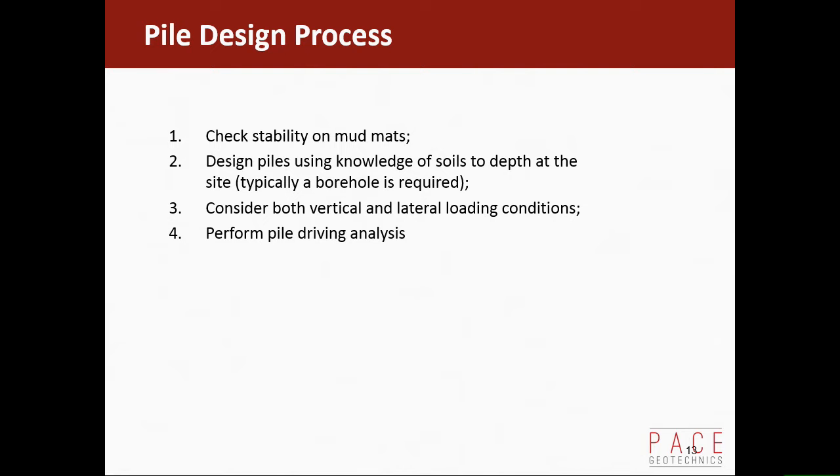One point I didn't make was that another advantage of a small gravity-based type structure is you just need to know something about the soils really in the top 5 metres. You're not too concerned about what the soils are doing at depth. And if you remember, I said in the lectures last year, site investigation, you can do seabed CPT, Vibracore, quite efficient to do. If you're going to drive piles, you really need to know what's down there, and the piles will be, say, 15 to 30 metres depth for a structure like that one I showed you. I think the ones we did there were about 25 metres long. So you need to do a borehole, which is another vessel going to do the survey. So that adds again to the cost of the structure.